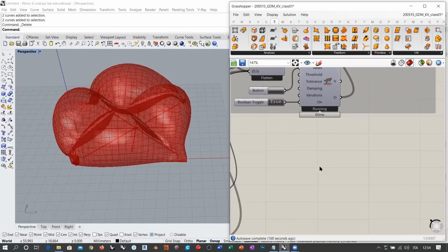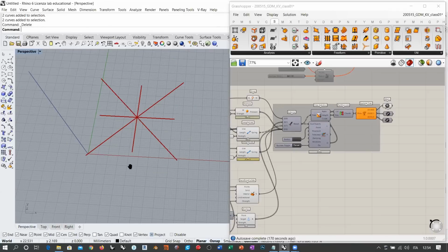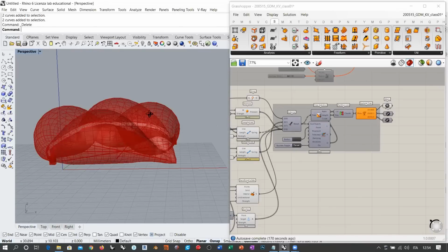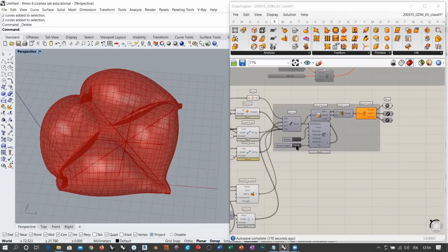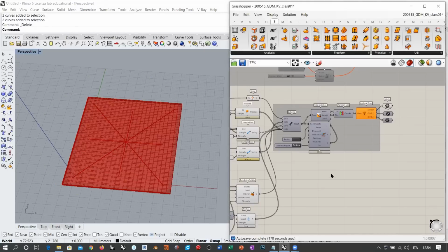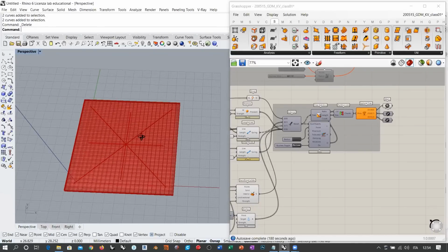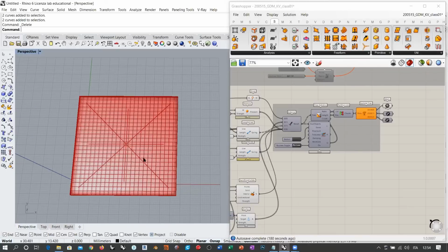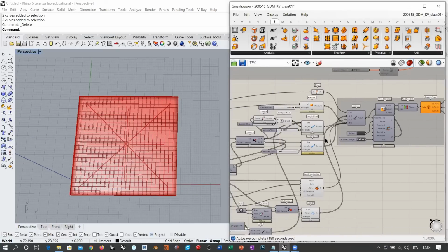Remember that, oh, well, this is something that we didn't observe. Eventually, I'm going to take a look at it right now. But keep in mind that this object was shifting to the left without reason, because the mesh is symmetrical, the boundary conditions are symmetrical, stresses and forces are evenly distributed, and they are symmetrical. Okay, so why is this object shifting to the left?